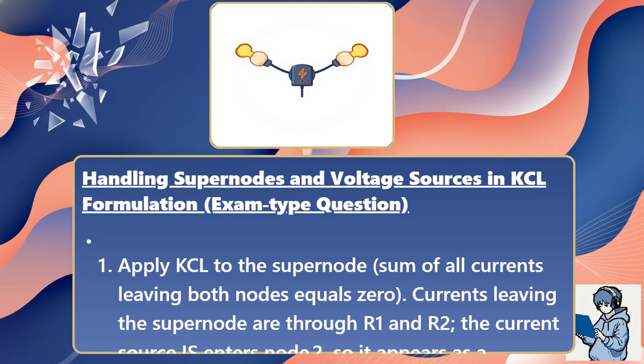Step 3: apply Kirchhoff's current law to the supernode. The sum of all currents leaving both nodes equals 0. Currents leaving the supernode are through resistor 1 and resistor 2. The current source IS enters node 2, so it appears as a negative term. (V1 minus 0) divided by resistor 1 plus (V2 minus 0) divided by resistor 2 minus IS equals 0. Substituting values gives V1 over 4 plus V2 over 6 minus 3 equals 0.